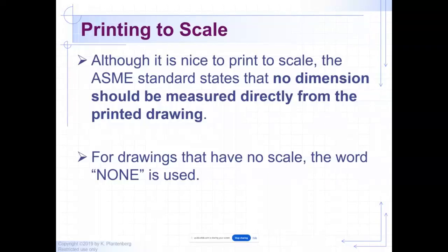Had some people do that, telling me that the framing guys didn't get with the contractor to find out what the rough size was for the windows. So they were just measuring off of the plan. Well, honestly, all you're supposed to get off of the plan is the center of where they're located, and you don't measure that off the plan because it's given. So anyway, it caused a big old mess. The contractor was just shaking his head like, really, guys? Got the owners all twitterpated and everything. They were trying to find a reason that my plan was screwed up. Anyway.